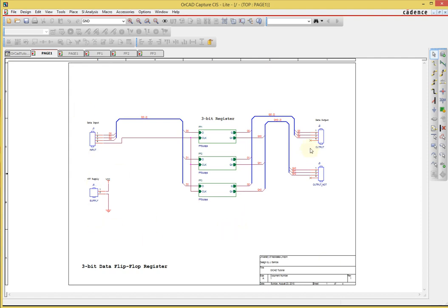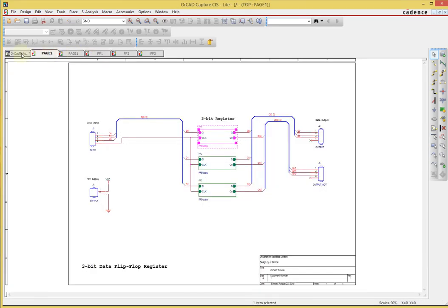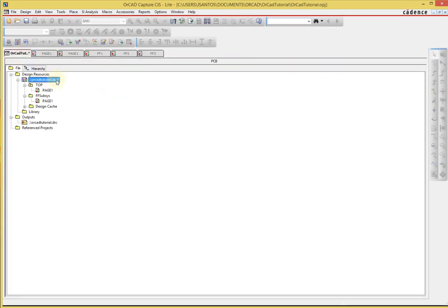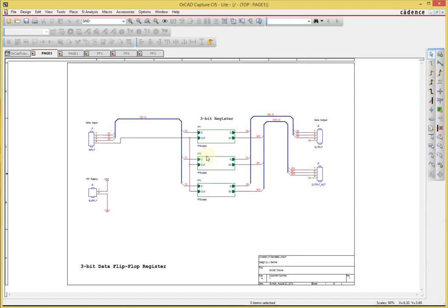So all of our connectors need footprints, and all of our gates, or the packages that these gates are part of, require footprints. Control S, save the project. So how do we assign footprints, and how do we pick footprints? This is now where the difficulty in using OrCAD begins, okay? Because there has to be a little bit of guess and check, and finding this information is not exactly obvious.